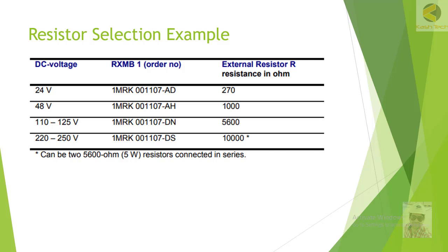So this is a key point that you need to check in such cases. Or even, for example, instead of 270 ohms for 24 volts, by mistake the delivered resistor is 150 ohms. In some cases there is maltripping without operation of any relay. The reason could easily be that the resistor value is not correct,